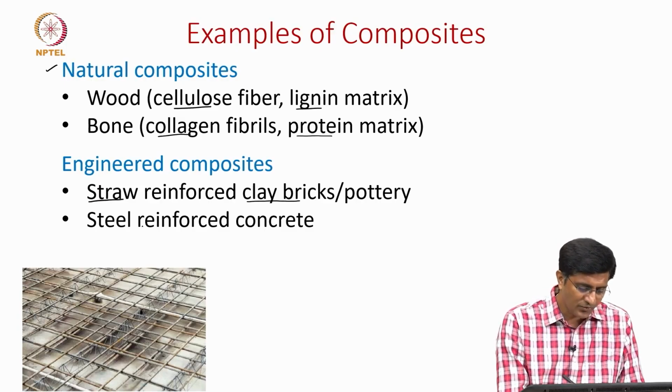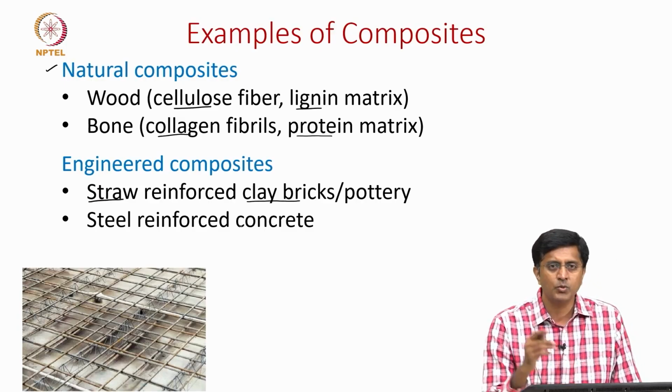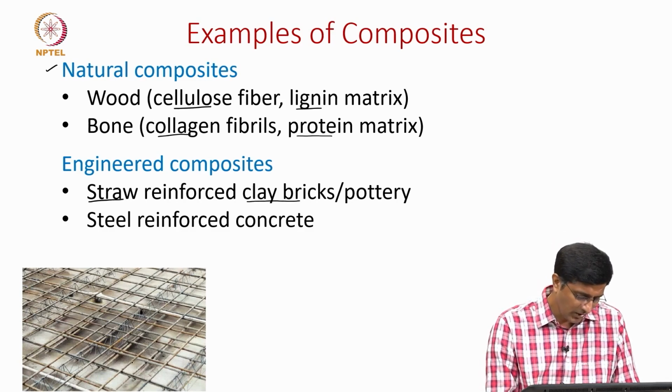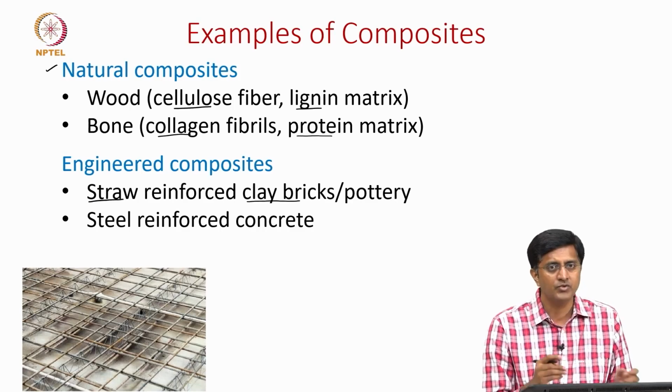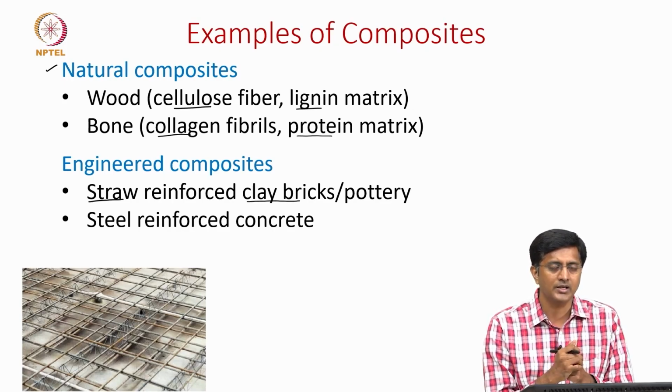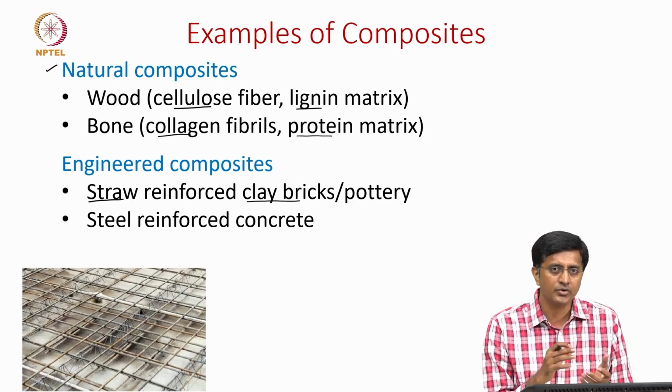But coming to the present age, we have been using composites such as steel reinforcement in concrete. Most of the buildings we have around are made up of steel reinforced concrete. We have steel rebars, which can take tensile loads, reinforced into the concrete. Concrete is good at taking compressive loads, but weak in tension. So, because of this steel and concrete combination, they can now take both tensile and compressive loads.